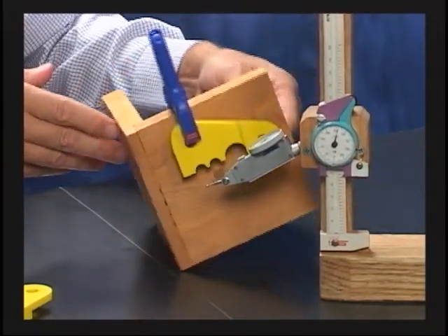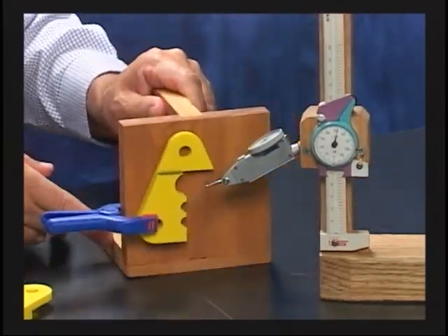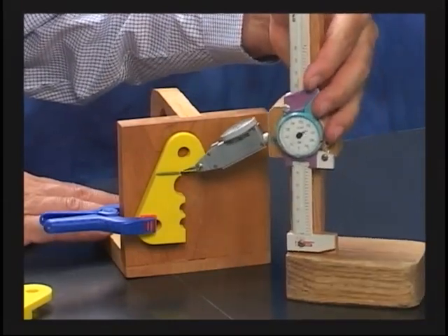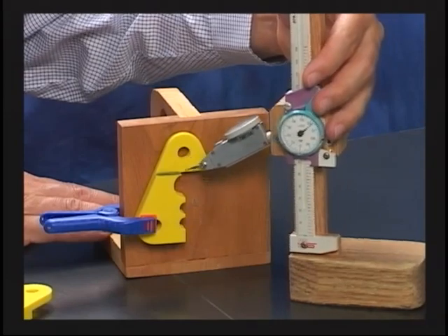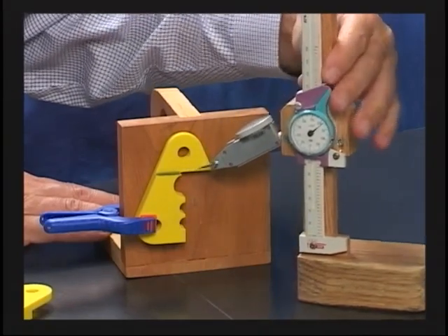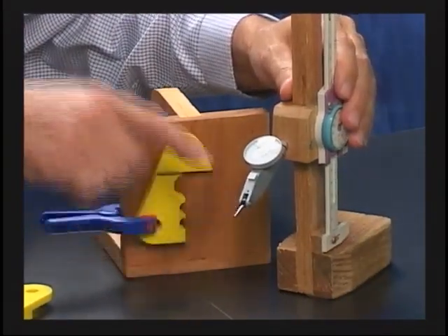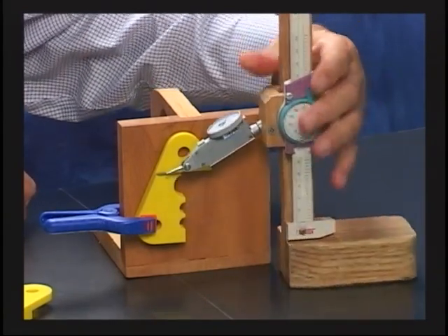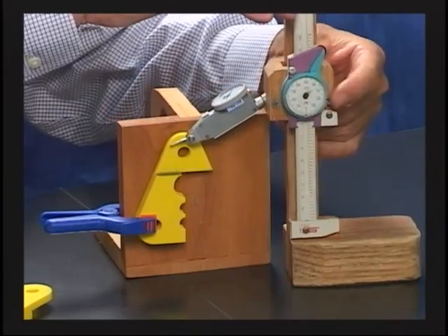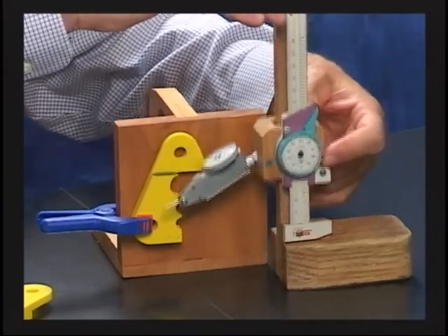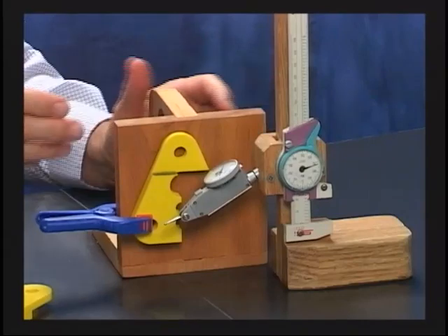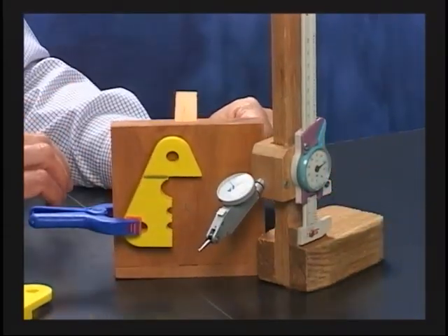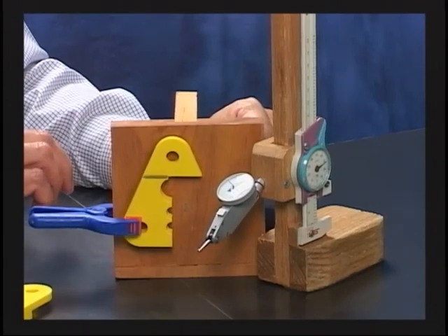Now, if I wanted to measure in any other direction, all I do is move 90 degrees. When I move 90 degrees, I'll come in and get a 0 on this face over here. Remember, that was my datum in this direction. And when I run my needle across here, do you notice that if my needle was moving, that needle couldn't move any more than 5 thousandths. That was my perpendicularity. And then from there, I can make any measurements I need to in this direction to center the hole and do my positions in this direction. So you notice how important it is to have a datum reference frame. If you have a datum reference frame, everybody sets the part up and measures it exactly the same way.